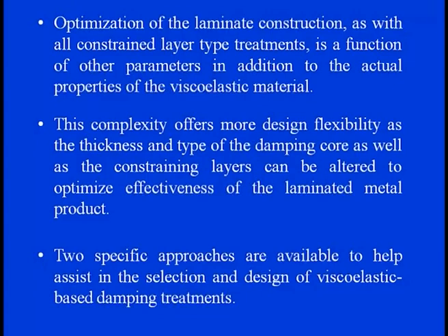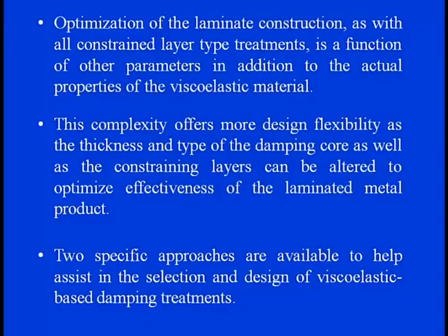But here we need to check what the thickness or the type of the damping cores are, or even what the constraining layers are, which have to be put in such a way that we can get optimum effectiveness of this product. So there are various approaches available, according to which we can select and design the viscoelastic based damping treatment for such problems.